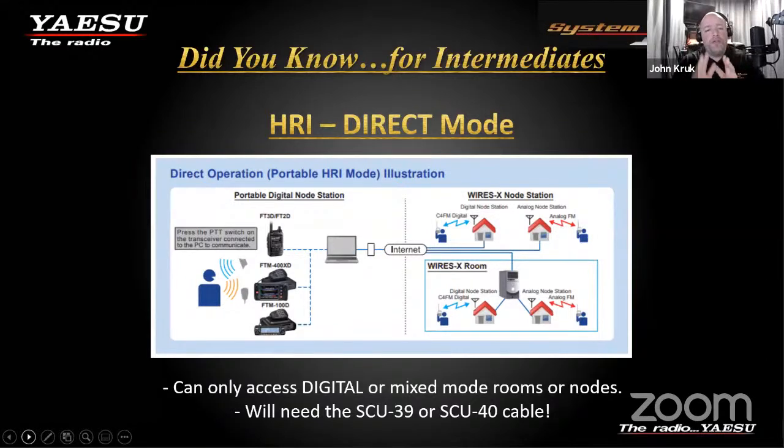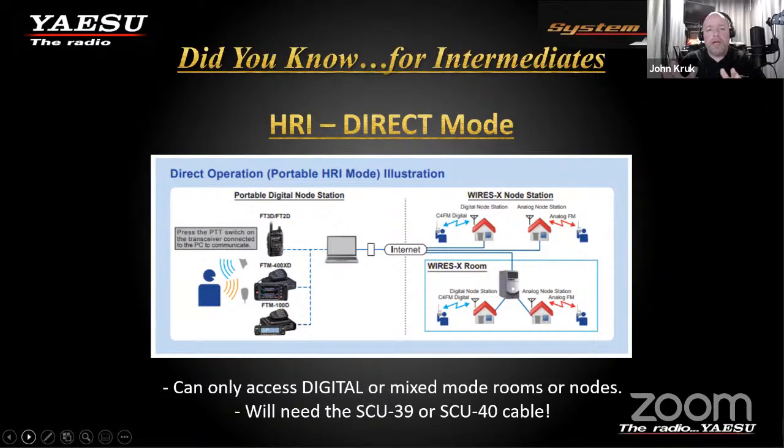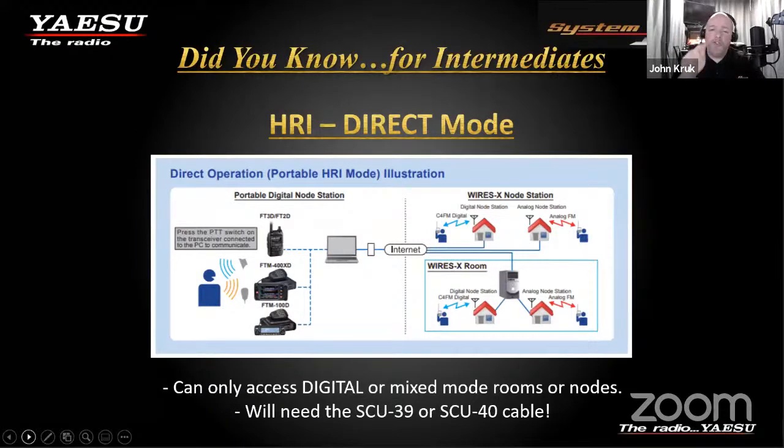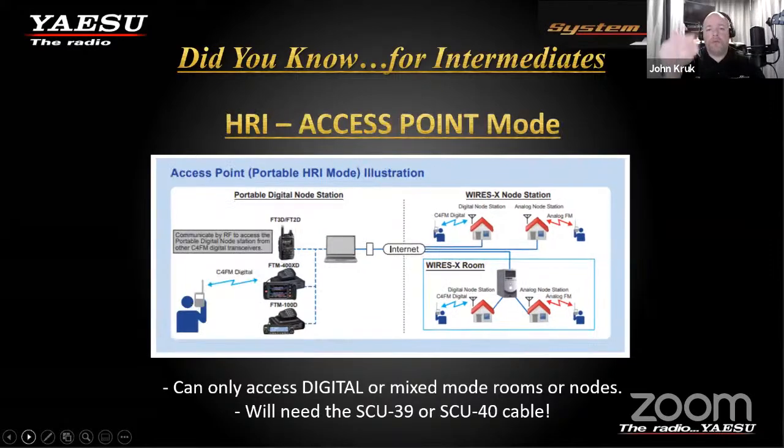And I'm going to tell you, you're doing a disservice if you're using HRI going into a mixed mode room, meaning analog and digital, and not using the analog cables. Because if there's analog users in there, what's going to happen is when you talk, the radios will key up, but it's going to be a dead key because you are not producing that analog stream. But as you see direct, once again, that's speaker microphone fashion.